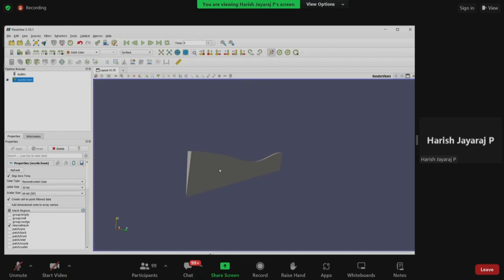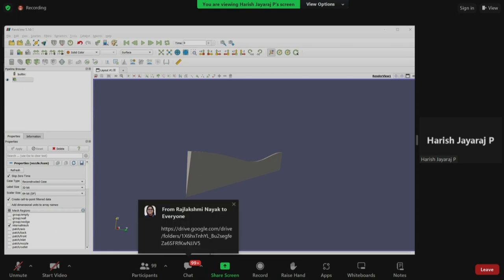It's more like doing a symmetry case. You might see when you use ANSYS Fluent or something, to take flow over a cylinder, we will just do the upper half and then reflect it to get the other half. That is exactly what we are doing here, but instead of taking a small slice in 2D, we are taking a wedge since this is a revolved part. Okay, so this is what we have here.